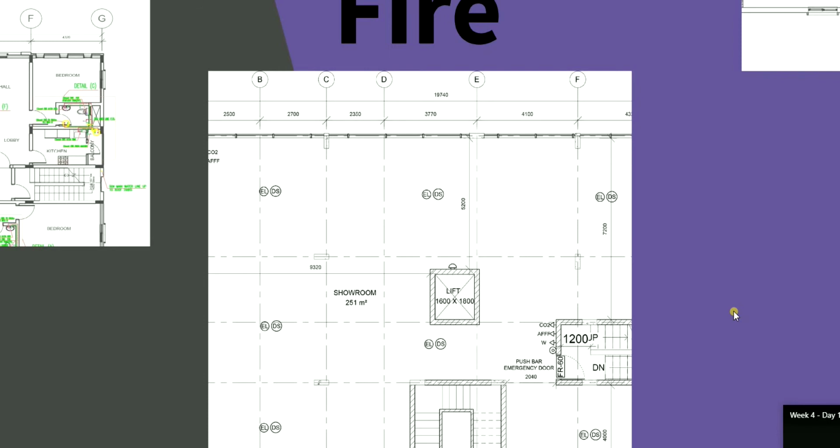Now, when it comes to residential commercial, there are two entities that I need to submit the drawings to. One is the municipality. For the municipality, I need to send the architectural and structural, and then I need to send to the civil defense, the General Authority for Civil Defense, whatever we call the fire drawing. I cannot start any commercial residential building unless I get the approval from the public authority for civil defense.